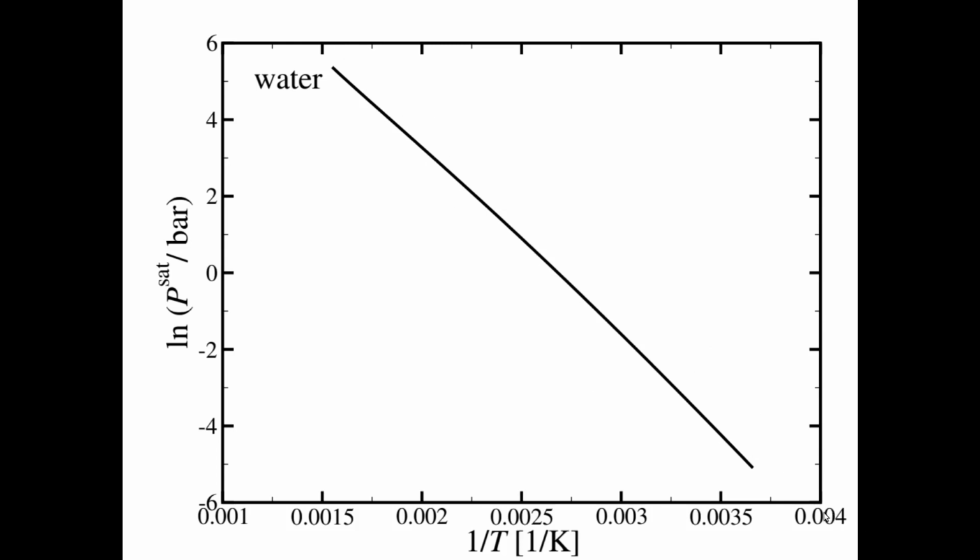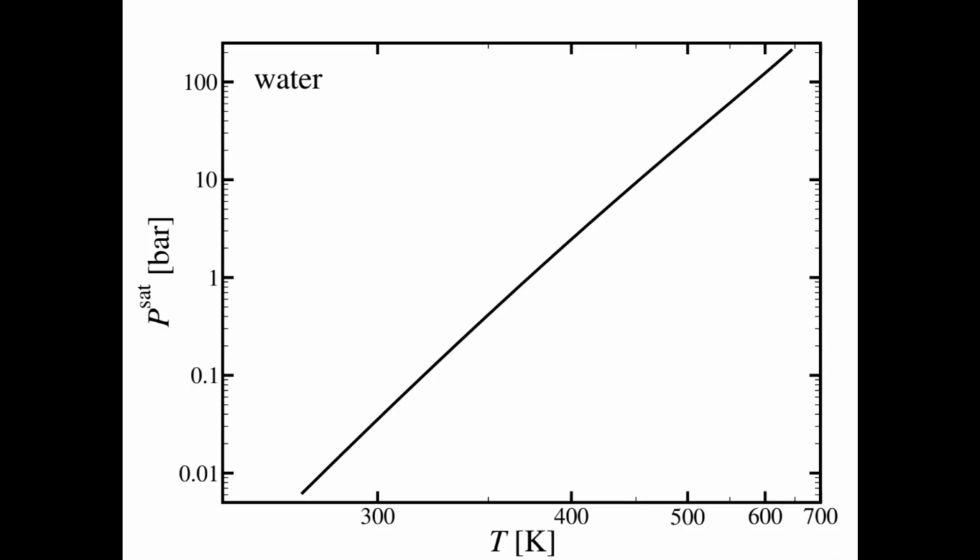Of course, it would be better if I had a third data point, I could fit an Antoine equation, and if I had more than that, then I could fit a Wagner equation over that entire range. But just by starting with our fundamental equation and getting to the Clausius-Clapeyron equation, we gain insight into how best to model vapor pressure data. Log P versus inverse T is key. Again, this is all the way from critical to triple point.